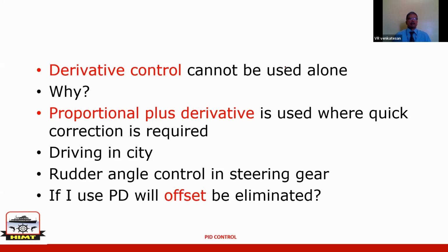Or in case, imagine water level in the boiler is going down very, very gradually. Then the output will be very, very small if you use derivative control alone. That output will not be enough to overcome, for example, friction in your actuator. So the entire boiler water level can go down and still you will get no correction at all.